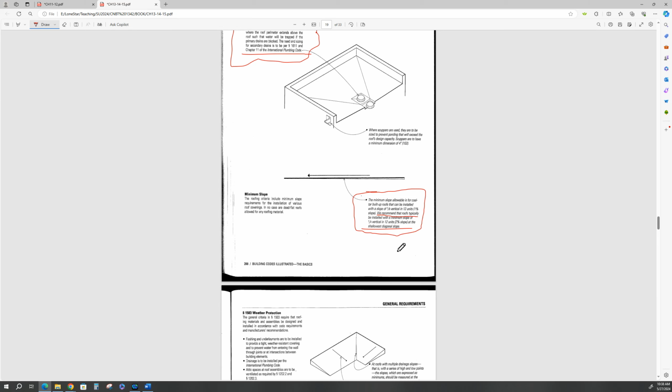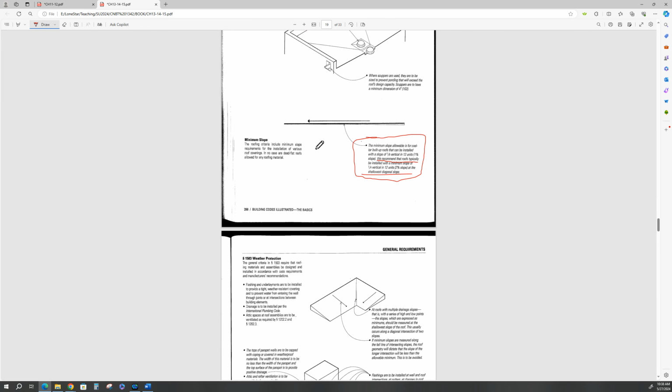You better check your local codes because we get a lot of rain. Most of your streets are only designed for 1 inch to 1.5 inches an hour rain. After that, things start to pond and flood. One of the engineering buildings that I used to work in had a roof collapse during a heavy rain because the roof drains up here got plugged up and it ponded and it collapsed. Pulled the joist right off the structural stuff. Really nasty job.